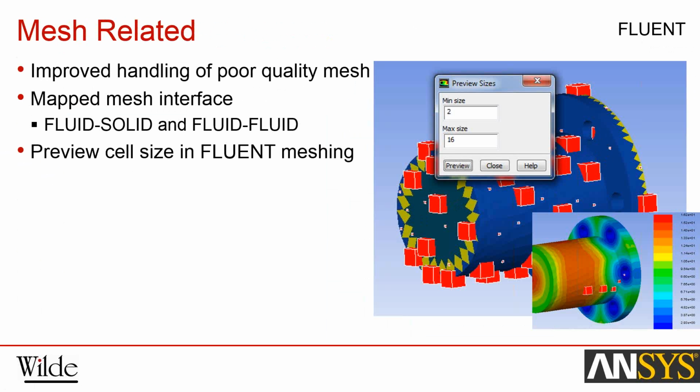But let's say you've already done the mesh and you've already got results. Again, you can look at your mesh element size on a contour plot and see, okay, my contour plot looks a bit patchy, but I think I've got a decent enough mesh over there. Or my mesh elements are too big in this region, which is why I'm getting some sort of discontinuity, or my contour plot looks very patchy and I need to make my mesh more refined.